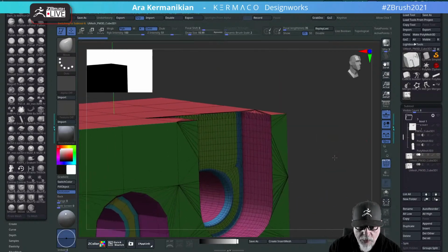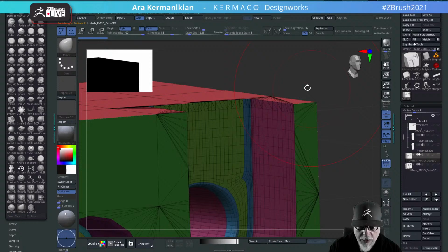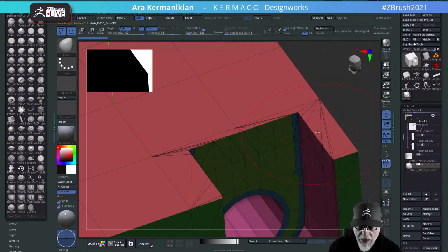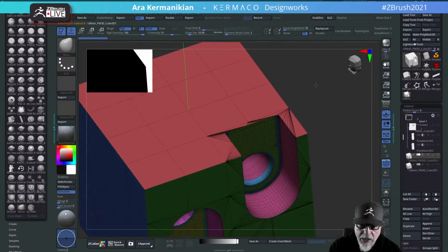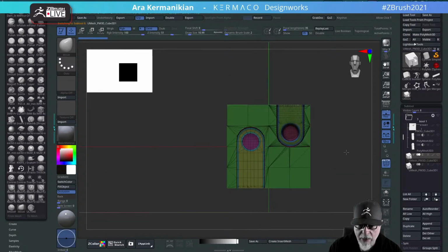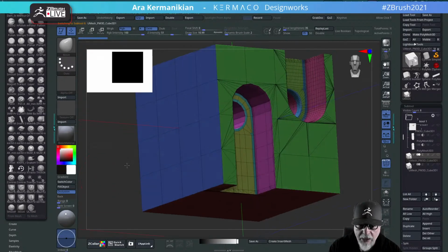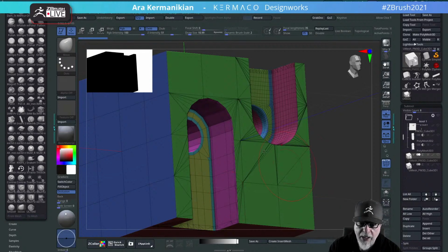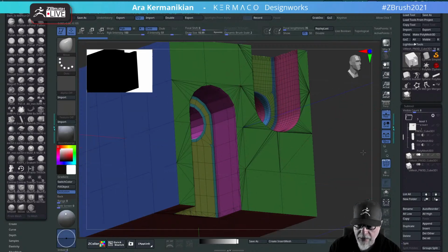So you see this new piece right here that had more topology. Now look at the difference in triangles. You can see here that there's a ton of triangles. Here there's less, right? So you've got all these little tiny slivers of triangles, and those are going to cause you a headache. All right. So when you're doing Booleans, make sure that the topology, meaning the density of polygons, is as similar as possible to all the parts you're Booleaning, and that way you get less complex pieces.